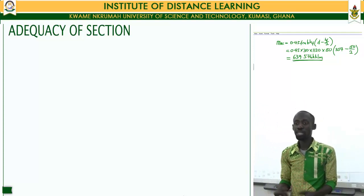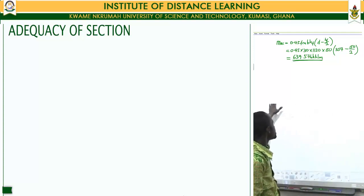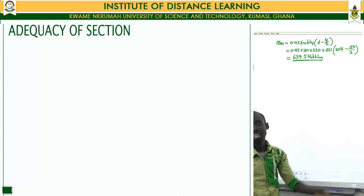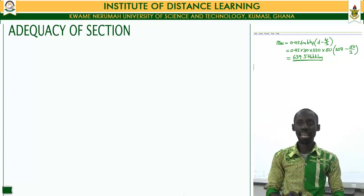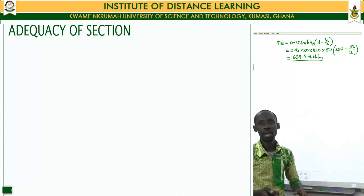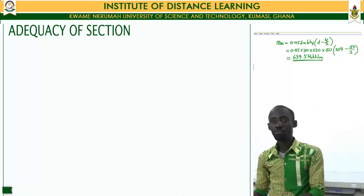Now, for us to determine whether we are designing our beam as a rectangular section or a flanged section, we should have our moment of resistance being greater than our applied moment, as we saw in unit 1. When I have my moment of resistance being greater than the applied moment, then it means that my neutral axis falls within the flange, in which case I can design my section as what? As a rectangular element. But if I have my applied moment being greater than my moment of resistance, then it means that my neutral axis is no more falling within the flange, but is falling within the web, and I'd have to design it what?